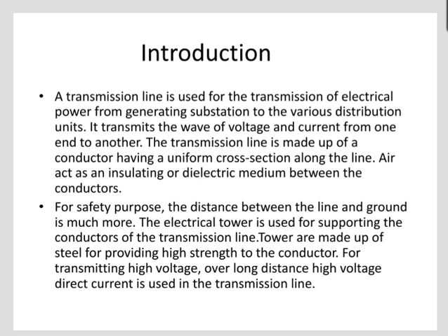The general idea is that transmission line effects become significant when the length of the line is comparable to or greater than the wavelength of the signal. A more specific guideline is one-fourth of the wavelength. If the interconnect length is less than one-fourth of the signal wavelength, then transmission line analysis is not necessary. The interconnect itself does not significantly affect the electrical behavior of the circuit. If the interconnect length is greater than one-fourth of the signal wavelength, transmission line effects become significant and the influence of the interconnect itself must be taken into account.